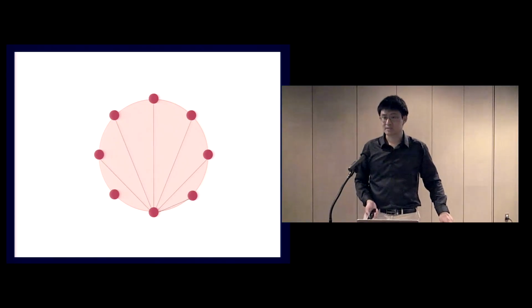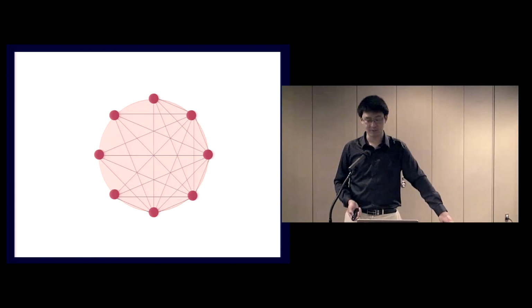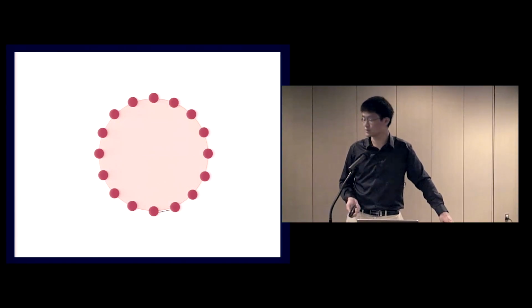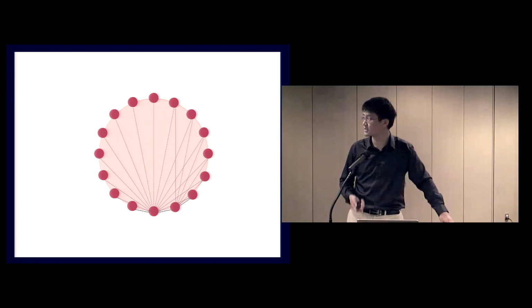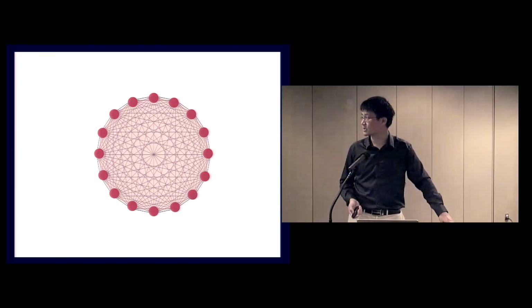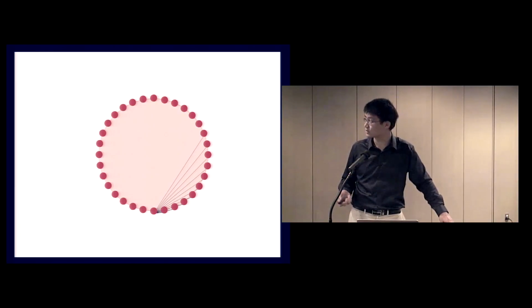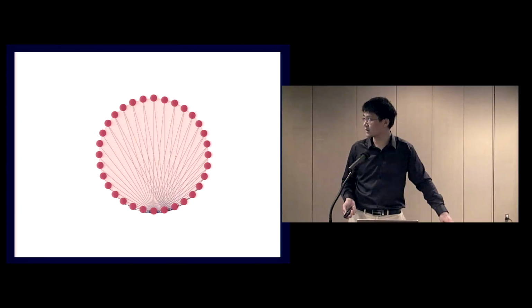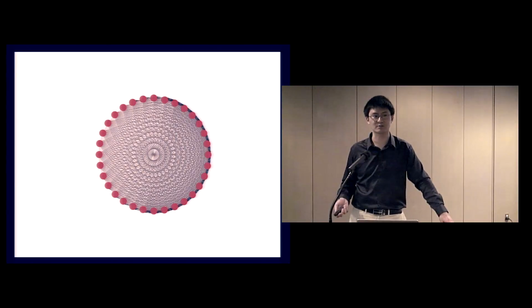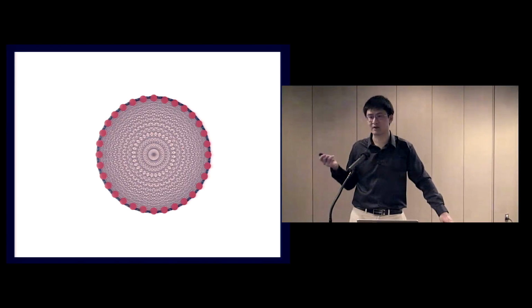So in addition to the sensing mode, we can also adjust the number of electrodes. Tomo used 8 electrodes, as you can see here, with the sensing paths shown. If we go up to 16 electrodes, we will increase the number of sensing pairs and therefore the resolution. But the big trade-off is that we're going to have to spend longer doing all the measurements. Taken to an extreme in our case, we can go up to 32 electrodes. You see there's a lot of sensing pairs and also correspondingly a much, much higher resolution. So with this kind of setup, we can get a very high resolution picture of the internals of the arm.